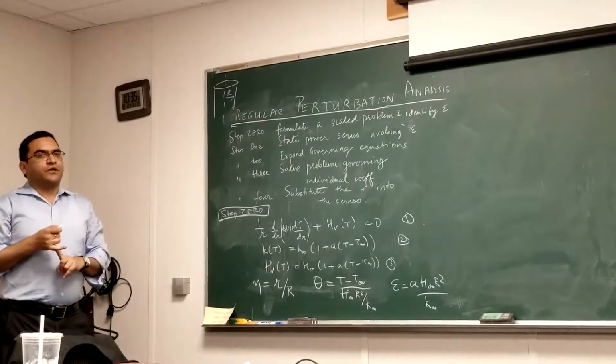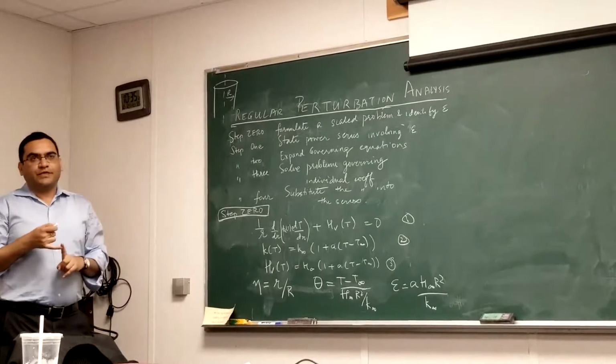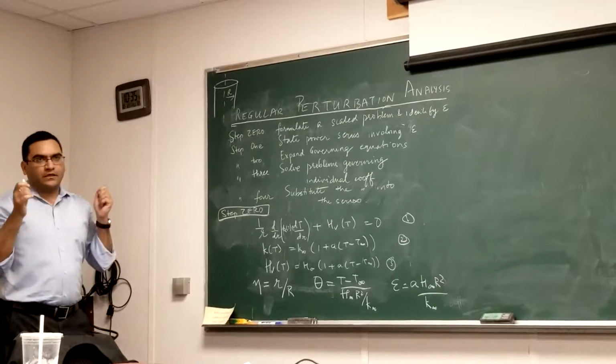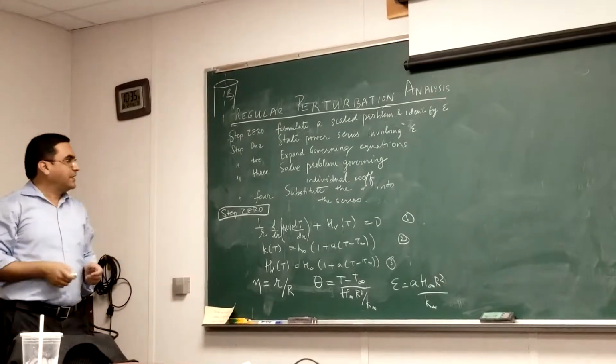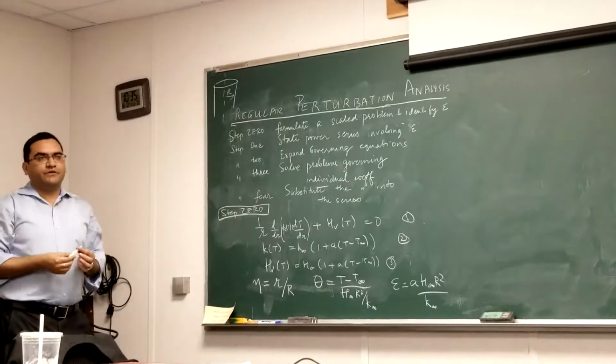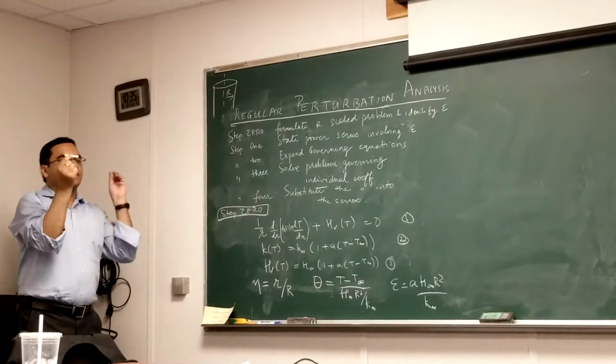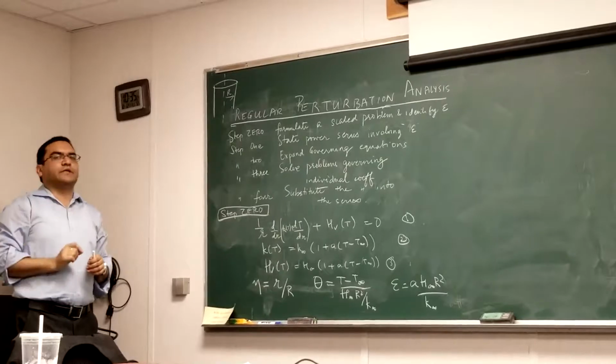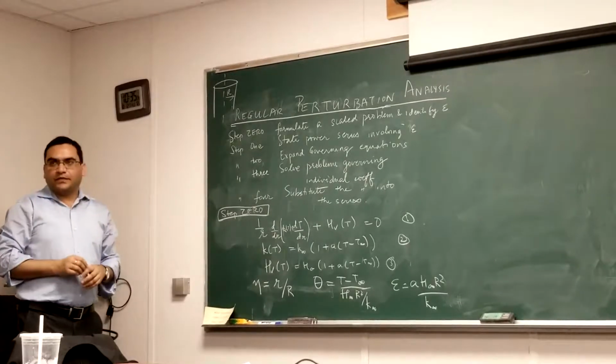So the best way to figure out what your heat transfer coefficient or mass transfer coefficient is going to be is to pick up BSL and go to your geometry. If it's flow around a cylinder, there are specific correlations. You look at those correlations, calculate the number and use it in an equation.